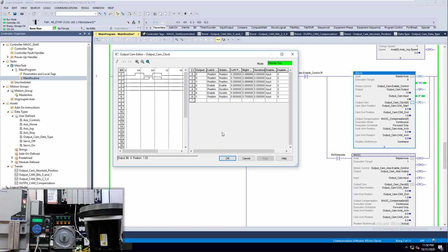If you understand the conversion rate of your servo, you're going to better understand what's happening in this, right? You cannot set any of this if you don't understand the way the servo is actually set up. That's again why we talked about the conversion constants, and we talked about the revolutions, and how we're rolling over and resetting every revolution.